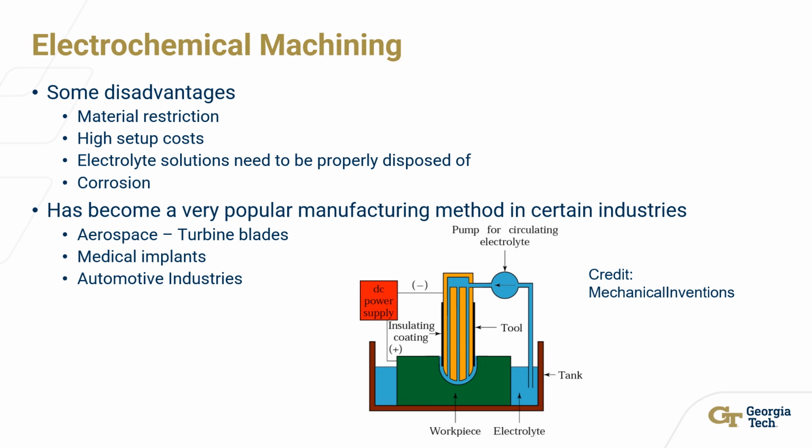It can only be used on conductive materials, like I said. There can be high setup costs, and you also need to deal with disposing of the electrolyte solutions in an environmentally friendly manner, and the tool can also corrode. But it's seen great success in certain industries like aerospace, machining the metal turbine blades, as well as the medical and automotive industries.